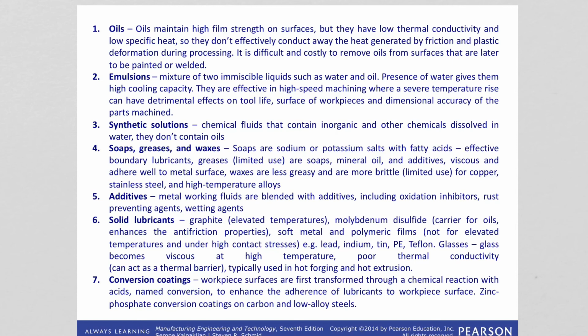And there are also some soft metallic and polymeric films. They have low strength, thin layers of soft metals and polymer coatings. These are used as solid lubricants. Suitable metals include lead, indium, cadmium, tin, and silver. And polymers are polyethylene, polytetrafluoroethylene. These are being used.